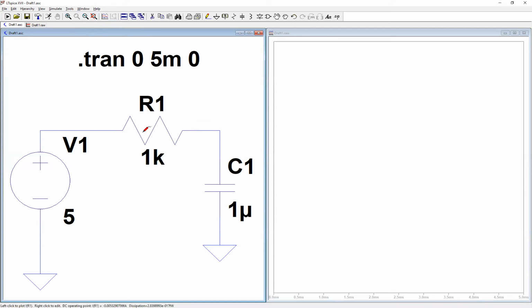You see now when I go to the circuit, there is one probe, the symbol of one probe. So if I want the voltage, then I have to click here, because this practically corresponds to the positive terminal of the voltmeter, right? And the negative terminal is always connected to the reference node. LTSpice does this automatically, okay? So you just have to put the positive terminal of the voltmeter. In this case, it should be here, right? Because I want to measure the voltage across the capacitance.